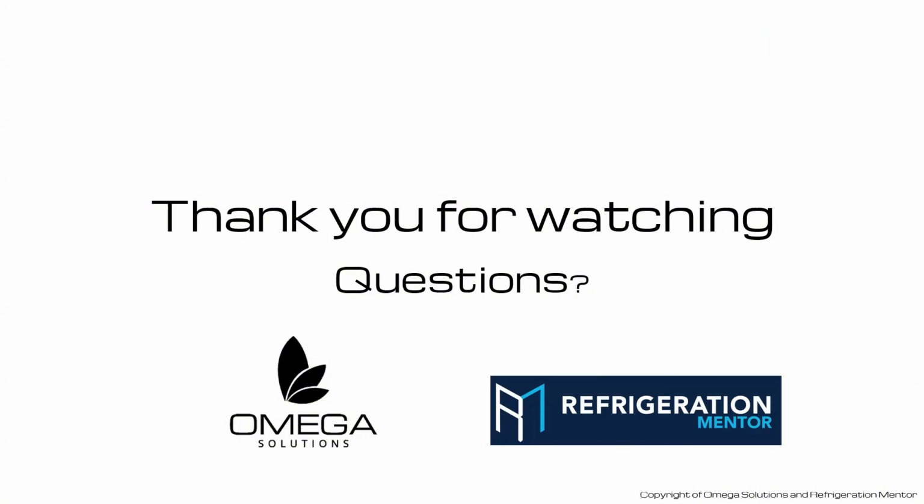Yeah, we've done that before, but specifically with transcritical CO2. As I did the training classes a few weeks back, I went through the training guides for Carrier's disposition. And for me, being in the field quite some time, it was new to know that our transcritical CO2 actually has an inverted trap at the compressor, which hasn't been standard through HFC models, right?